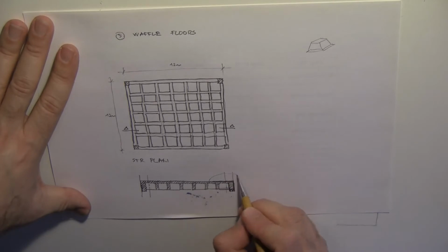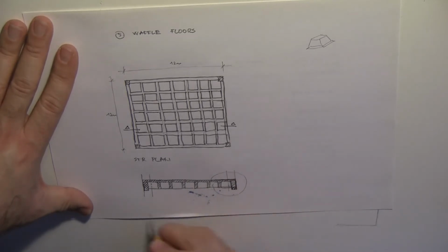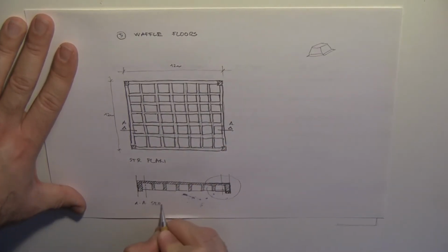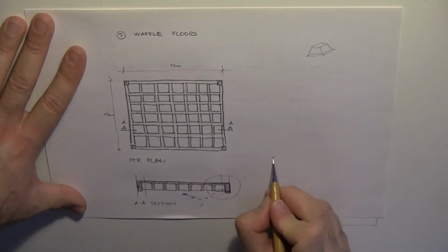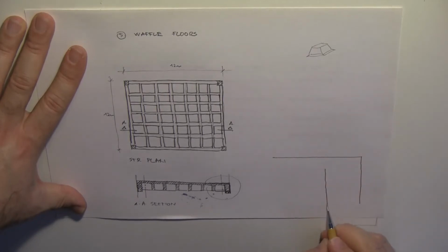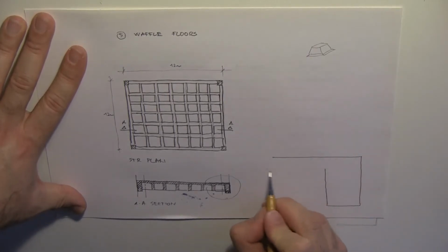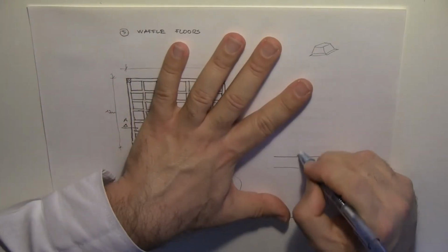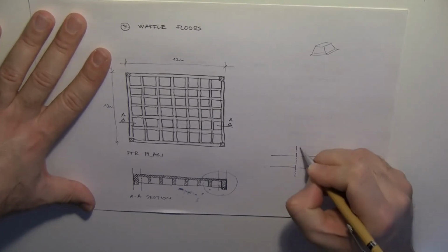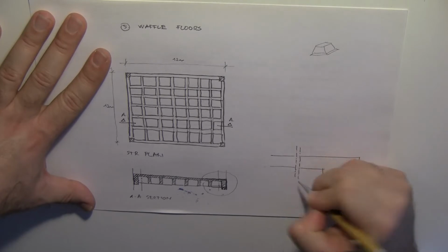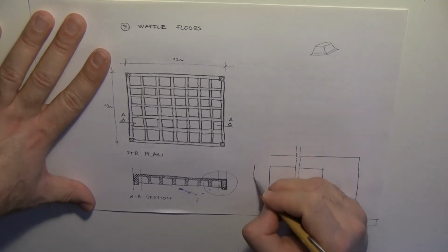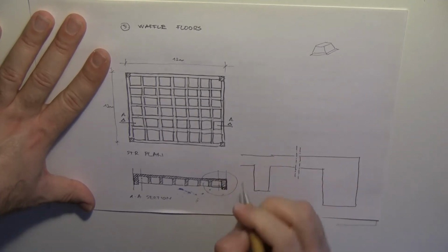Let's draw here as a detail. Let's name it firstly. That is an AA section. And now it will be seen something like this. This is my main beam. I'm going to use the same trick. I'm going to cut it from here, and I'm going to draw dashed and dotted lines here to represent that the floor continues that way, but it is too long and I do not want to spend unnecessary space for it. That's why I cut it.